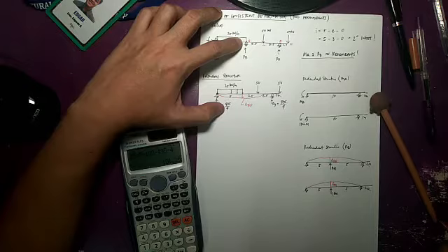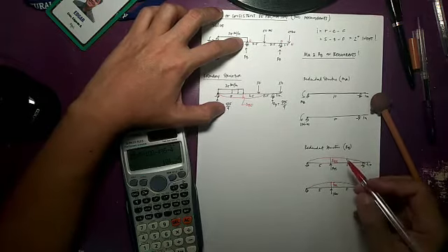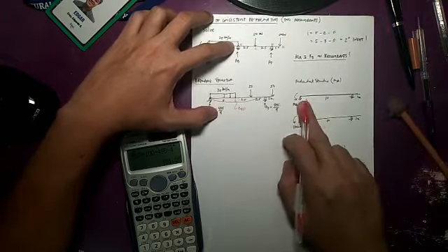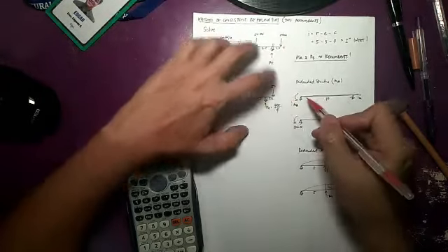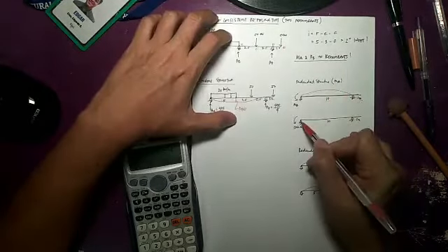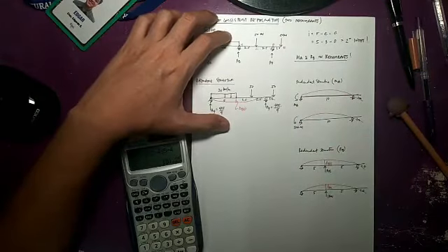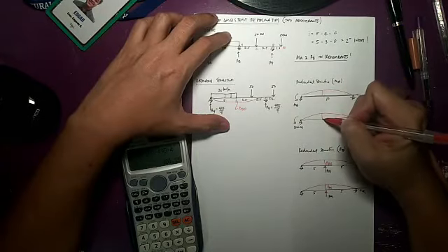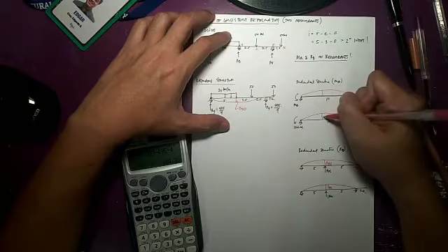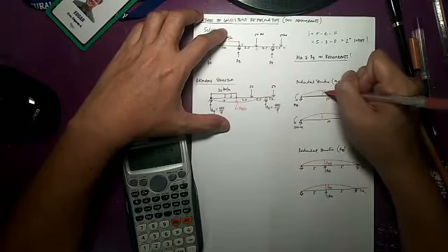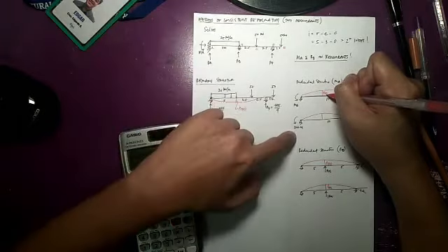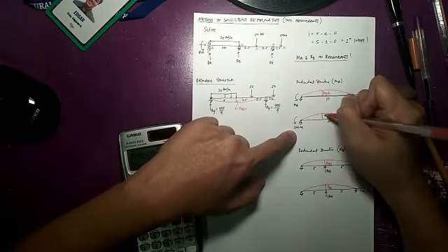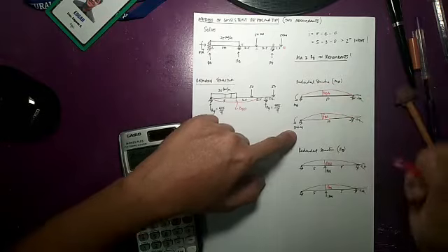Okay, now, likewise, due to the redundant MA, due to the counterclockwise, the beam will deflect like this. Likewise here also. So the deflection over here, the deflection here would be delta at B due to the unit load moment at A. This is FBA.